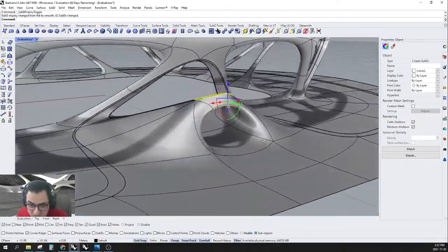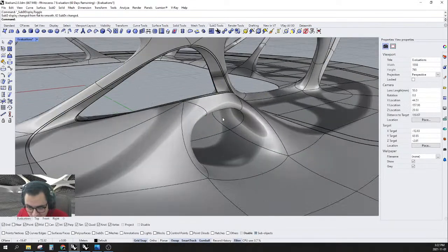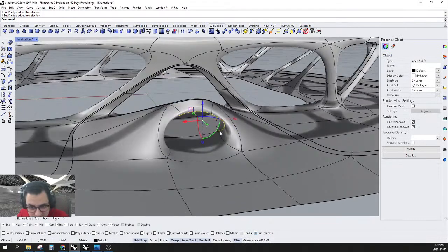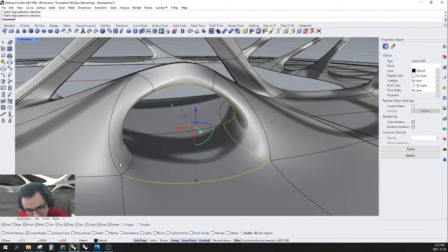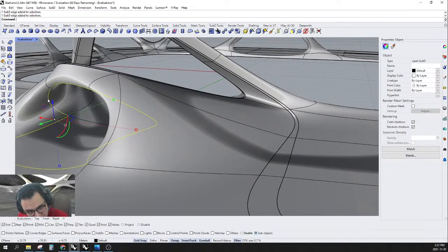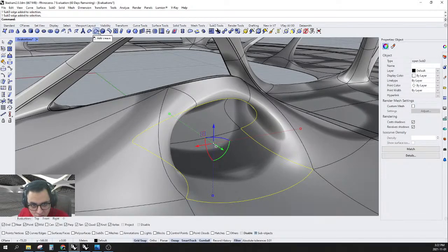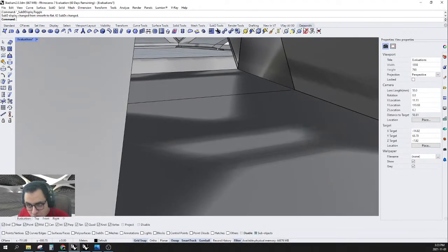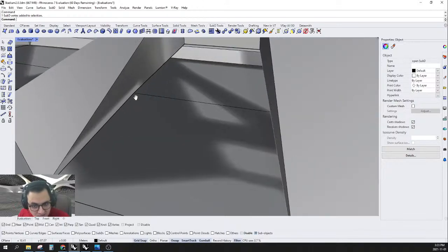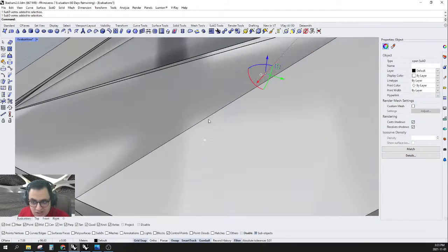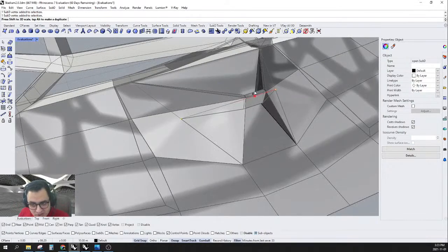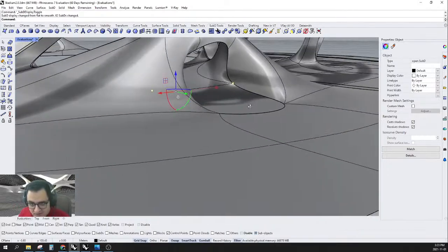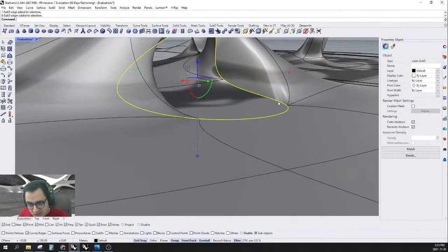That's kind of perfect. And after that, I would like to create the same thing, but I will select this and this, and instead of selecting this, I will go away like this and go back to this. So when I bevel or add crease, it will give me a look like this. But in this case, I would like to make it narrow, so I will select this vertex and this vertex, and maybe scale them to the inside a little bit, so they will look kind of like this, I think. And after that, simply right click and bevel.